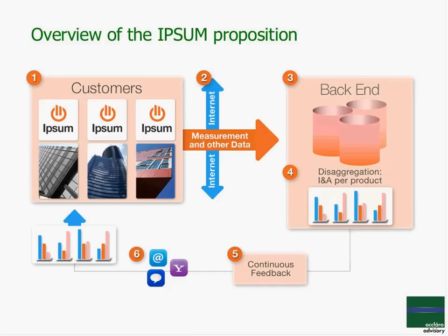provide real-time information in terms of how energy is being consumed and where some of those changes can start to take place. The mechanism itself: there's a set of buildings, and at the moment the system has been developed predominantly for office and retail-based organisations. The data itself is collected in a disaggregated manner. What that means is the algorithms that have been written as part of the energy data collection process are able to separate out the consumption of energy by individual product types. So we can tell what amount of energy a computer is using versus the printers, versus the lighting, versus the air conditioning systems, and so on.